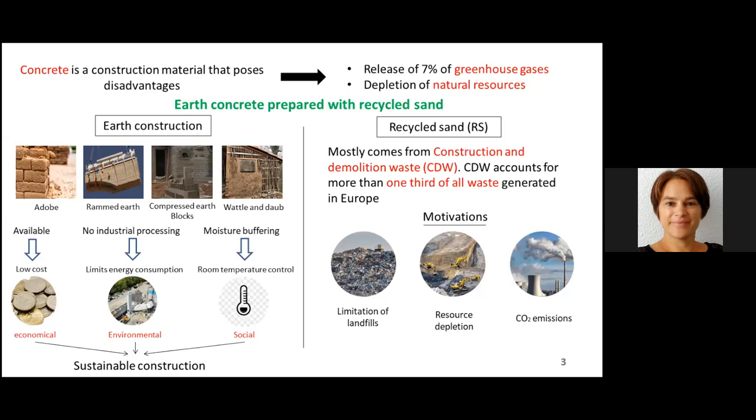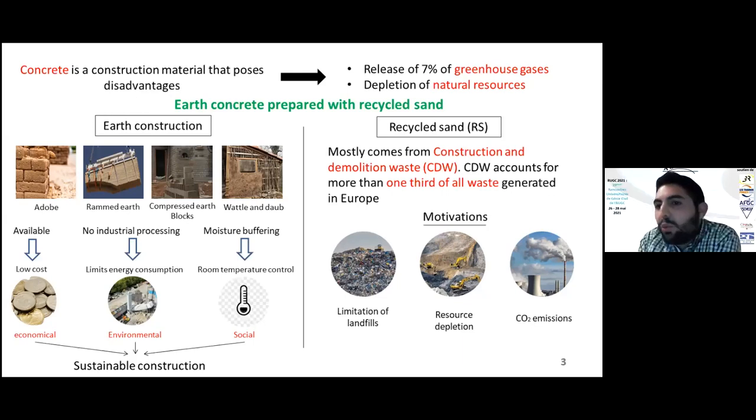Let's say we used the recycled sand without any pre-saturation, and we have 30% of natural sand and 30% of recycled sand. If we put here 3 liters of water and here 3 liters of water, the recycled sand mixture is going to absorb all the water. So it's not going to be workable like the natural sand. So the increase in the initial water content leads to the decrease in strength. And another thing, the recycled sand are full of cracks and full